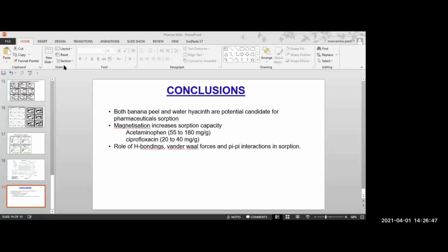Thank you. The first answer to your question is that we are not using wet biomass for the biochar preparation, because biochar preparation through slow pyrolysis or fast pyrolysis requires dry biomass. We are sun drying the biomass because in India there is a lot of sun and heat, so we use direct sun drying to not increase the cost. And sun drying is providing the desired results. For the second question, can you explain it again? It is related to the commercialization of this process.